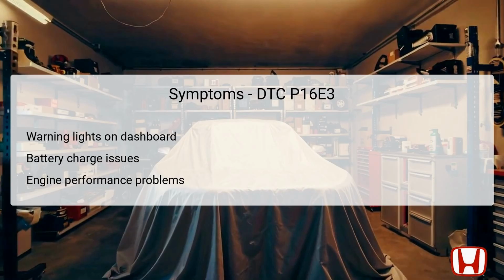Additionally, drivers may experience battery charge problems, noticing that the vehicle's battery isn't powering systems effectively or is discharging more rapidly than normal. Another significant symptom could be engine performance issues. Erratic engine behavior may occur due to the PCM not receiving correct data related to battery voltage and health. These symptoms are crucial indicators that warrant immediate troubleshooting efforts to diagnose and resolve the underlying problems.